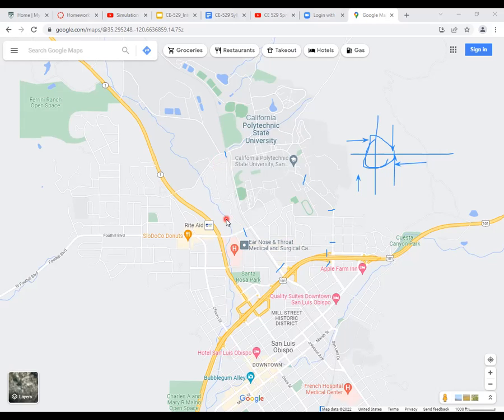The peak hour traffic flow that's coming in is going to give you an idea about how much traffic is coming in from here. But you still don't know where they're going. So what my student had to do is look at, during the morning peak hour, which parking lots are getting filled up. Those become your destinations. So you need to get some sense of your OD flows. It's not an obvious problem, by the way. As your network size grows, this is not necessarily obvious.